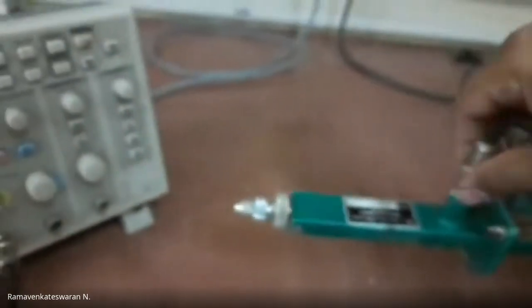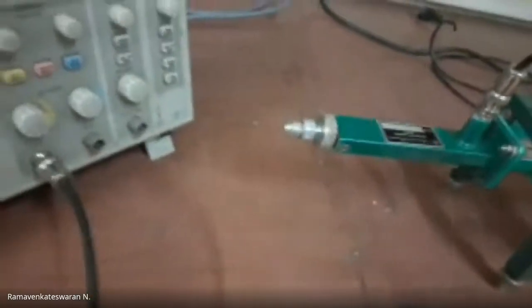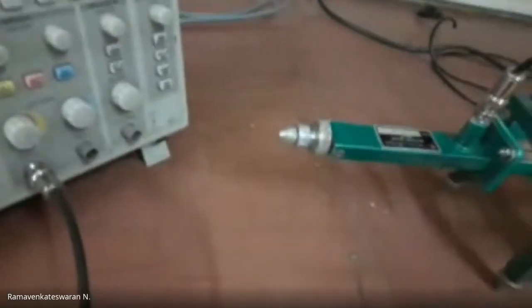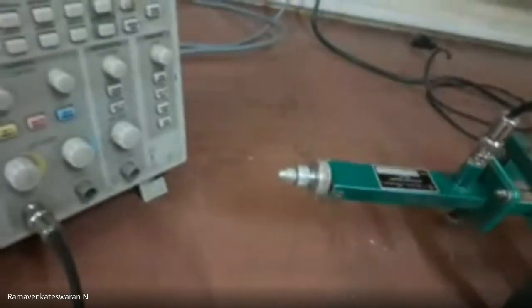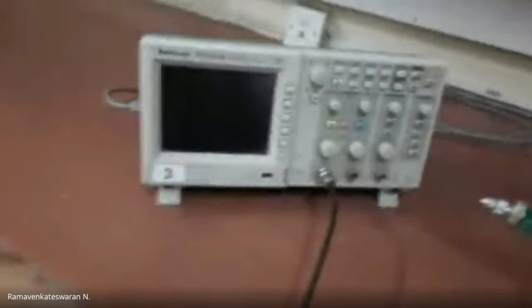After that, I have this crystal detector, which is a cable connected to the oscilloscope. The other part is matched with the impedance of the waveguide, so that no reflection takes place. To protect against reflection going back to the klystron source, I have an isolator, which will allow only one direction. Then I have the oscilloscope, to see whether I'm getting a microwave signal. This is the basic setup.